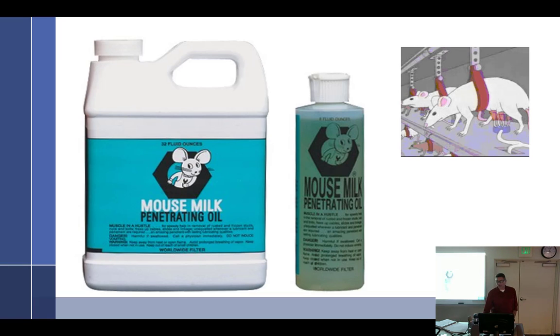And on any turbocharged system, I'll take some of this mouse milk penetrating oil and definitely lubricate around the wastegate, especially because wastegates take a beating. If you've ever worked around any exhaust system, you know you can't even pull the exhaust nuts off. That's why professionals use a Sawzall to get your catalytic converter out.